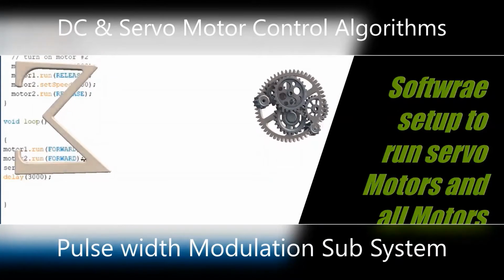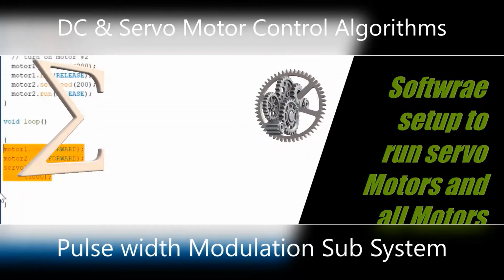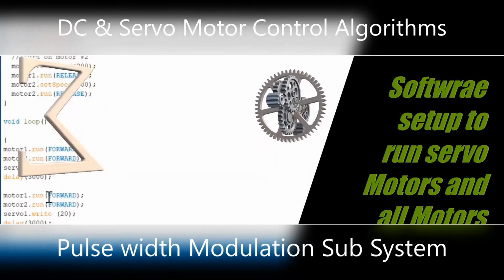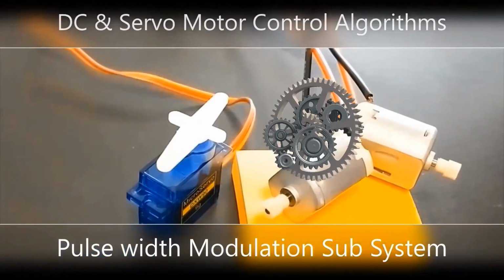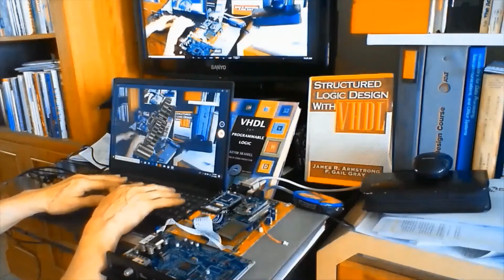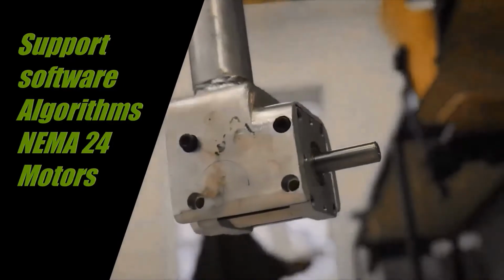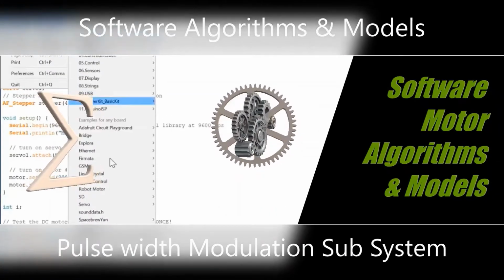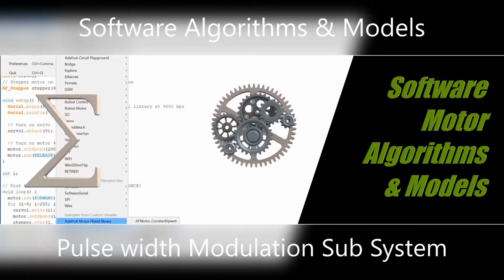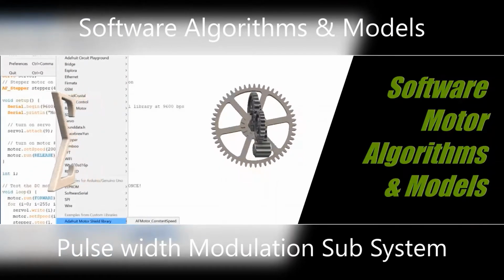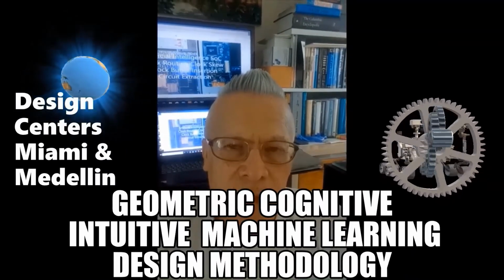The motor system paradigm uses MOSFET drivers with 1.2 amperes per channel current capability and can draw up to 3 amperes peak for approximately 20 milliseconds at a time. It also has much lower voltage drops across the motor, so as to get more torque out of the batteries, and there are built-in flyback diodes supported in this system.